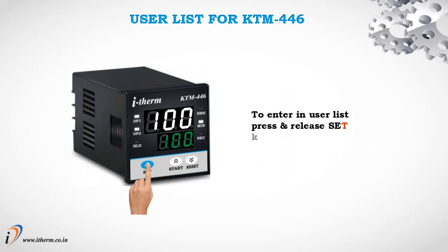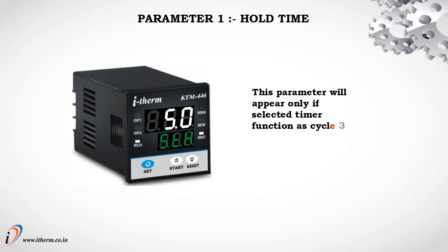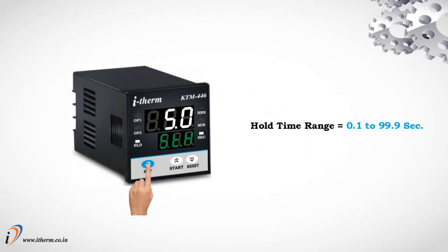User list for KTM 446. To enter in user list, press and release set key once. Parameter 1, hold time. This parameter will appear only if selected timer function is cycle 3. It sets the hold time between output 1 and output 2 in cycle 3. Hold time range 0.1 to 99.9 seconds.